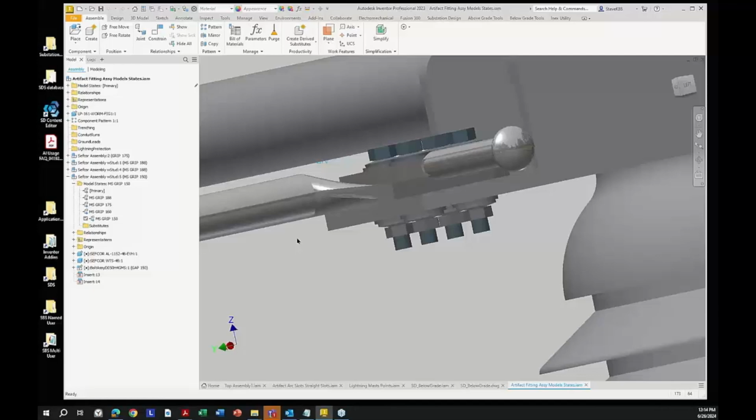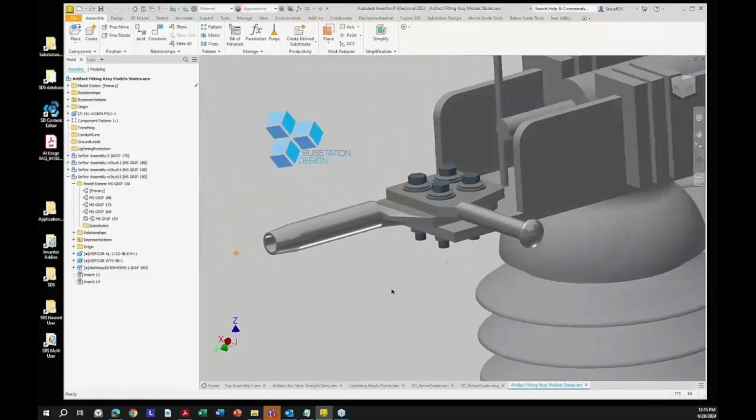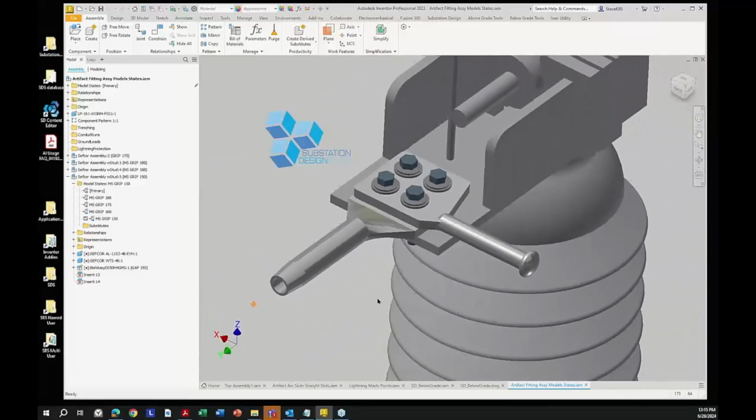So what it's changing is the length of the bolt. It's going to change the description of the bolt, the part number of the bolt, and that's going to be in your bill of material correctly. So if I go ahead and change this to, I don't know if I have the highest number, I can change it to a higher number, and I can have that proper description for the right size bolt for that grip.